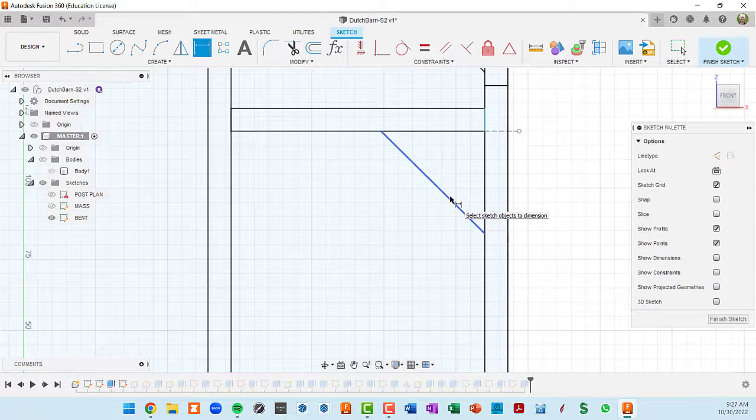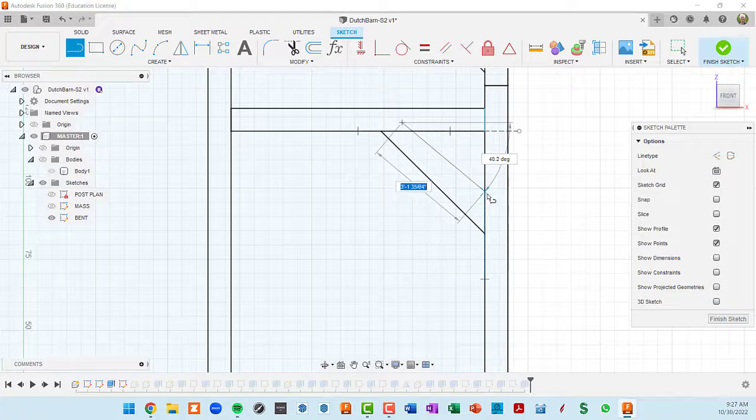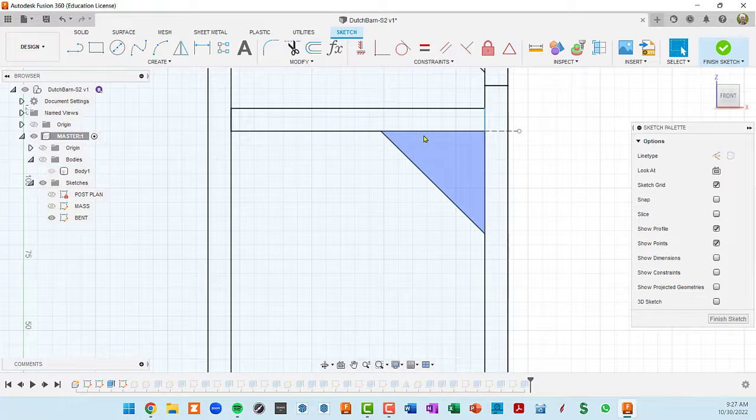Now our brace timber is actually 4 by 6. So I need to get another line here. So I press L for line. And I'm just going to put this somewhere off in space and actually make it, well, you know what? I guess I'm going to go ahead and intersect this line. Why not? Okay, so I'm going to intersect here, and I'm going to intersect here, and I'm also going to tab over and do 45.